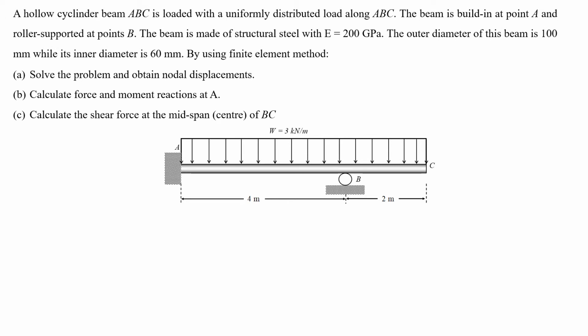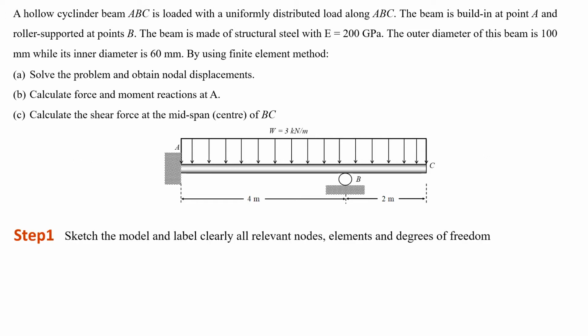Then, calculate the force and moment reactions at A, and the last one is to calculate the shear force at midspan of member BC. The first step that we have to do in this case is to sketch the model and to create the nodes, elements, and determine the degrees of freedom.